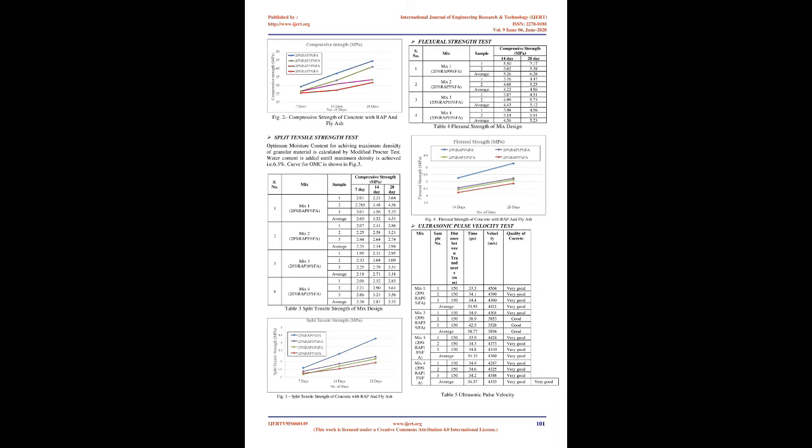5. Methodology adopted. Tests of reliability and strength of concrete materials. The strength of concrete depends on the quality of the materials used. The properties of cement, natural coarse aggregates, fly ash, RAP, and fine aggregate are tested. Cement is tested for fineness, specific gravity, and initial and final setting time. After gradation of aggregate as per MORTH provisions, optimum moisture content is also calculated. Then RAP materials and fly ash are tested as per MORTH provisions.